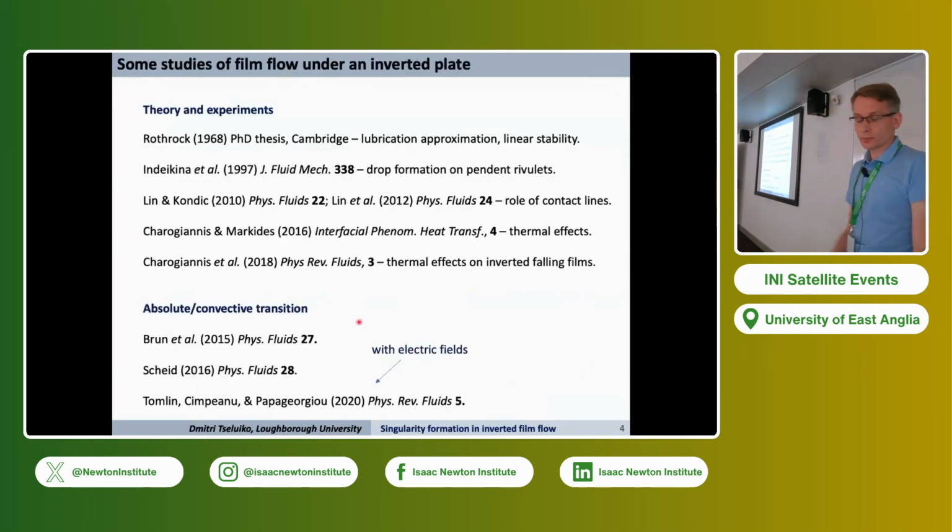Okay, let me first mention some previous work on inverted liquid films. Rothrock, in his PhD thesis published in Cambridge in 1968, analyzed stability of an inverted film based on a lubrication approximation, and he obtained onset conditions for the formation of the waves as well as their wavelengths and speeds, and he compared his theoretical results with his experimental work.